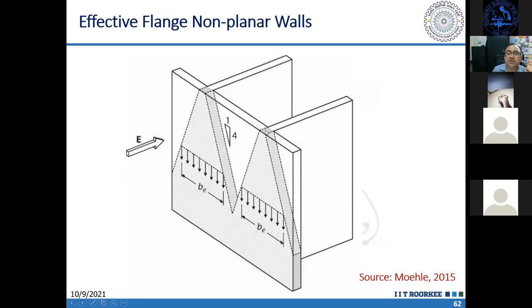And we can see that this will be very small at the top, equal to the thickness of the web. And as we go down, due to dispersion, this will involve larger width. The maximum it can involve is 1/10 of the height, or the physically available width, because it cannot go outside the shear wall. So within the shear wall, whatever is the maximum available, or 1/10, that much we can use at maximum.